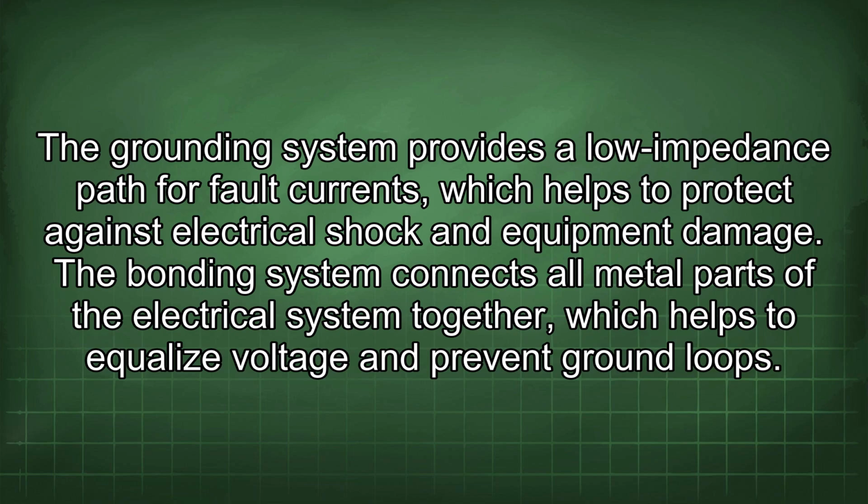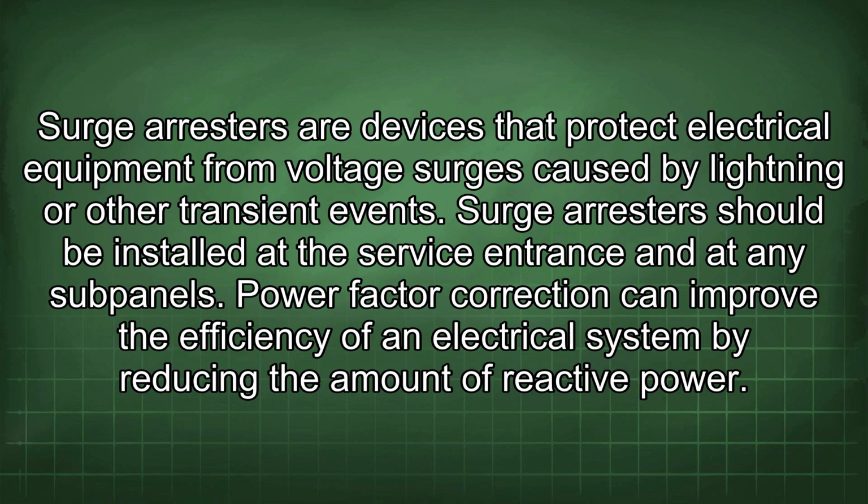Surge arresters are devices that protect electrical equipment from voltage surges caused by lightning or other transient events. Surge arresters should be installed at the service entrance and at any subpanels.